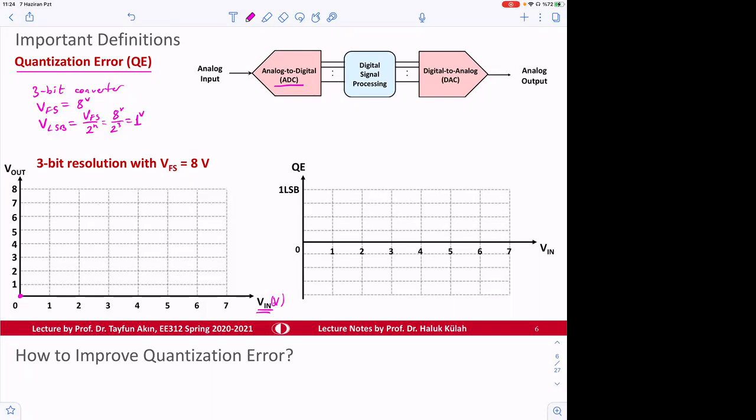Now we will call this V in, and we will call this V out. The device, maybe you will be giving a pure nice sine wave here, but here there's going to be a representation like this of that signal. For 3-bit, of course, this is going to be maybe 8 kinds of steps.